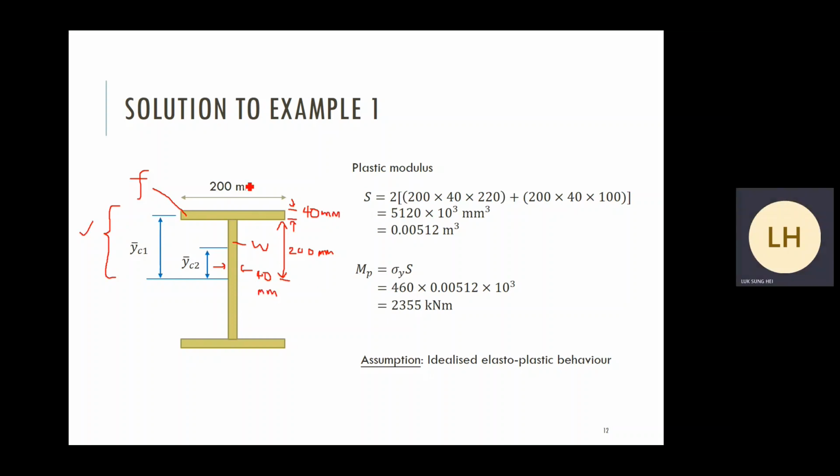And then based on our calculations, we can evaluate plastic modulus first, S. If you know the plastic modulus, S times yield strength give you back the plastic moment, MP. So firstly, you can evaluate our plastic modulus. Take a look on the equations. At the beginning, we have our number 2. These two represent we have symmetric cross sections. We need to multiply the answer by 2 so that it becomes one whole section. That's why we have a 2 here for the symmetric properties.